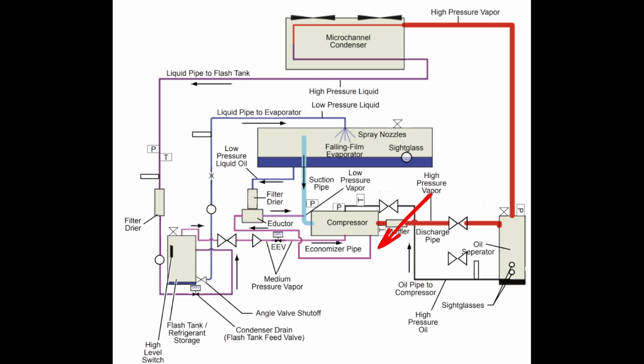So one of the modifications you'll see with a YVAA, if you're comparing this particular schematic, the field procedure was to move that hot gas line over here to the outlet of our separator, and that stopped the vibration issues with cracking the line and the heat issues, as well as we got far less oil latent gas going over to there, so that it didn't impede our ability to draw in oil latent liquid from our evaporator.